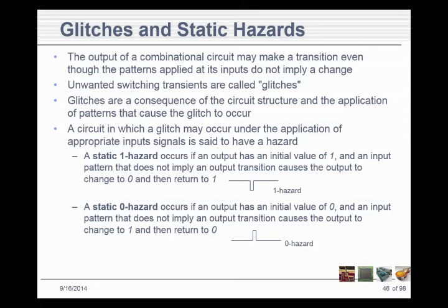It is time in little chunks. It's like every 10 nanoseconds, maybe. Every 10 nanoseconds, it'll go out there and sample all 32 lines. It might take it a few seconds to do that. And then it'll put out there it was a logic 1 or a logic 0. And then it goes back and samples all those lines, and puts out there it was a logic 1 or a logic 0. So it can't keep up with it in real time.